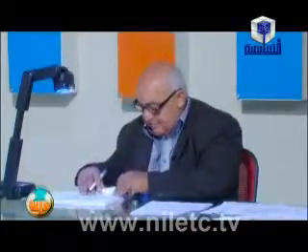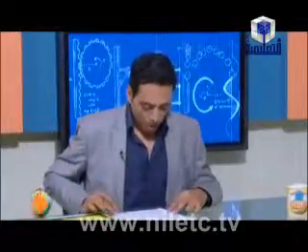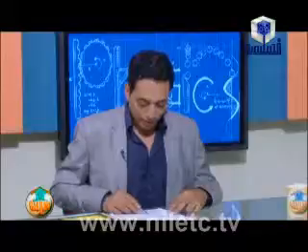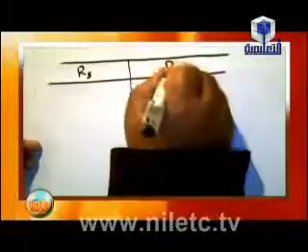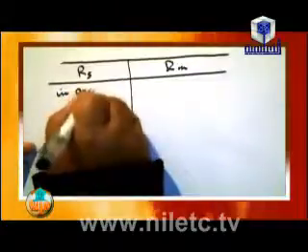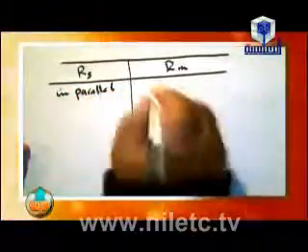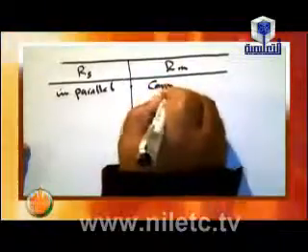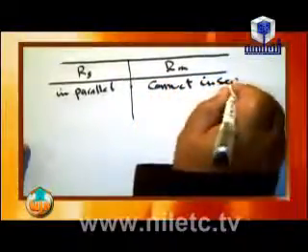And also compare between shunt resistance and multiplier resistor from the point of view of the method of utilization for each. The difference between shunt resistance RS and multiplier resistance RM. Shunt resistance is connected in parallel with the galvanometer, and multiplier resistance is connected in series.